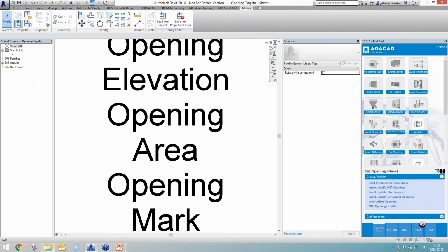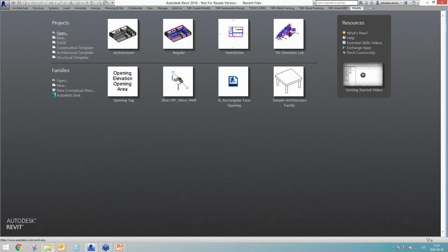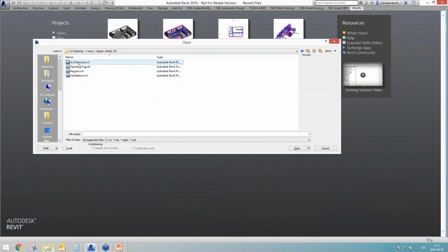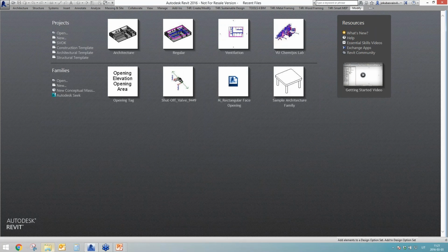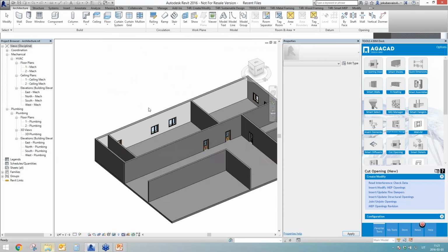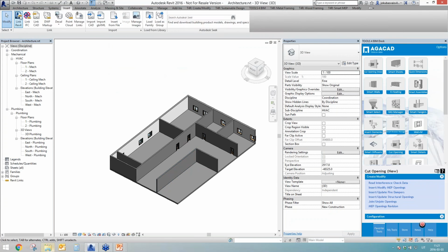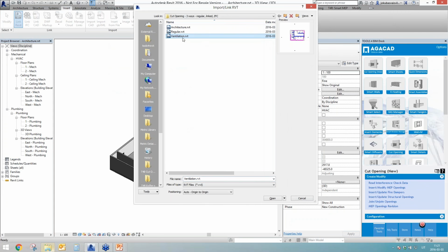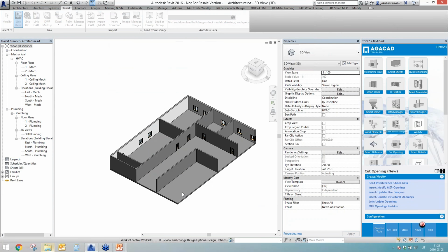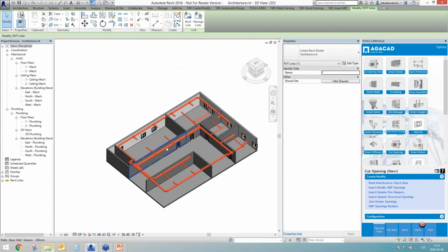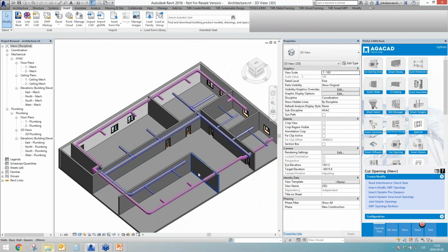If you will have something different, I will open the file where I have only the architectural model. So I'm opening it. This is the model, architectural walls, and I'm linking the Revit file that consists of ventilation. So I'm opening it as well. And as you can see, I have the link over there and the regular Revit files. So the workflow looks kind of the same.